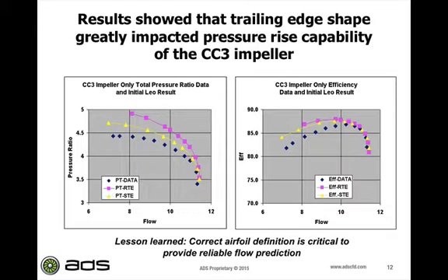So what's the learning? What we learn is that correct airfoil geometry is critical to the performance of this specific centrifugal compressor. It will impact the pressure ratio highly for this design. What's special about this design? This design has a back sweep of the trailing edge of about 45 to 50 degrees. Okay, so we identified one of the causes why the analysis is so different from experimental data, because we did not really include the right geometry in our simulation.